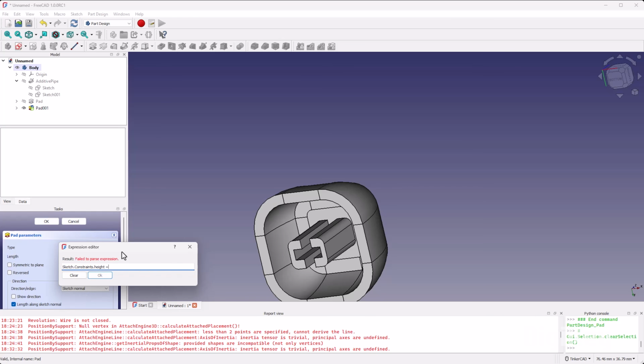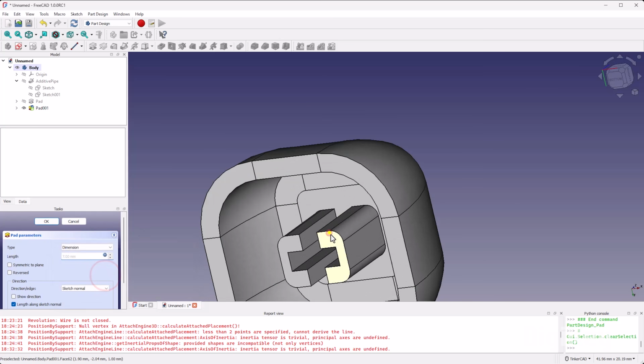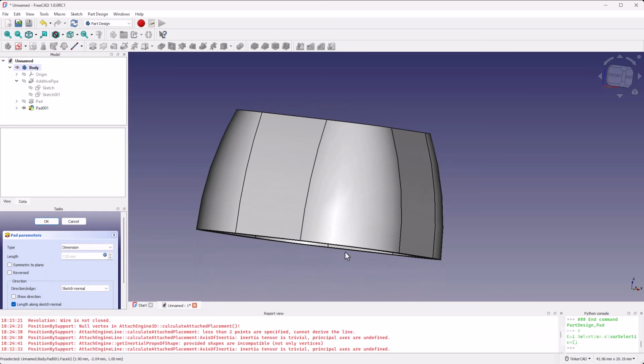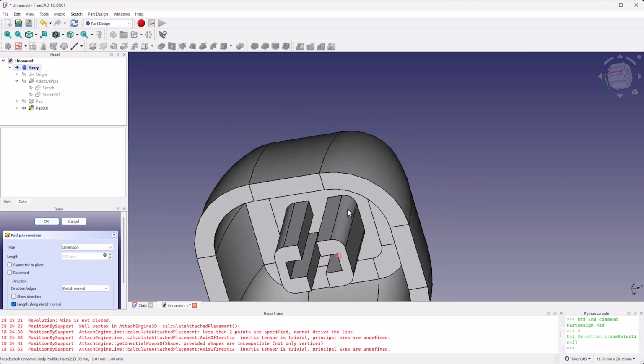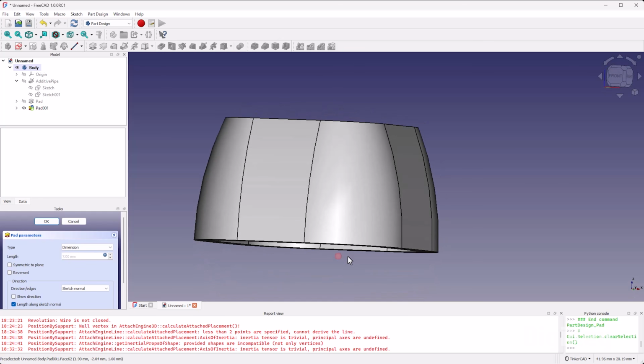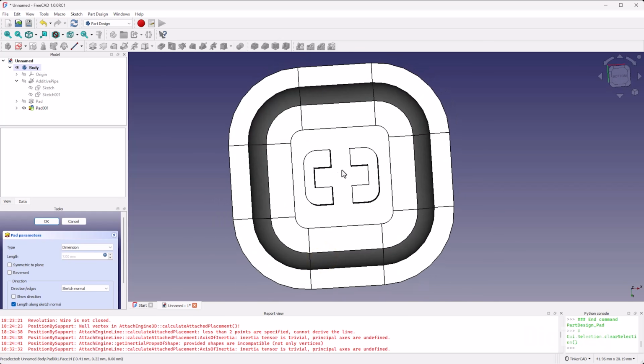We're going to subtract, not equals, subtract sketch dot constraints dot top thickness, because we want to remove that thickness from where we started. That was 2 millimeters. And then we're going to subtract out 1 millimeter. Click OK, and you can see that's now padded down, and it doesn't quite reach the bottom there. So that keycap should work and cover the switch as needed, and the stem still fits in here.